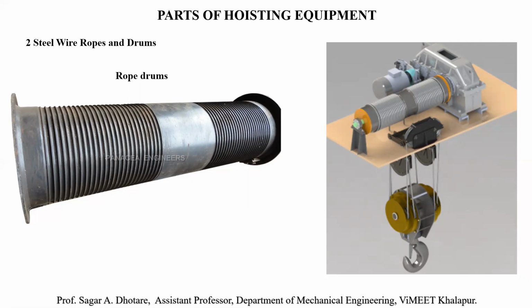shaft. The drums for a steel wire rope are made from cast iron. More rarely, steel casting or weldments are used, as the size is very huge or the loading capacities should be greater, or due to some environmental condition. Based on that, steel cast or weldments are used. With regard to the friction in the bearings, the efficiency is to be considered as 95%. The drum diameter depends upon the diameter of the rope.